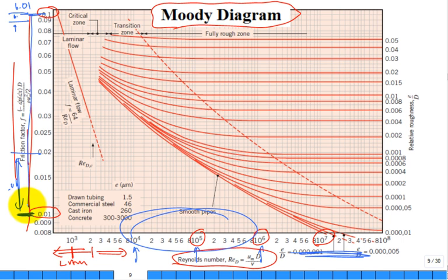Okay? All right. Hopefully you see that. Actually, you could even tighten it down even further, but that just limits it. All right. So now we have this region, laminar flow. The friction factor is a constant divided by the Reynolds number. If you are using the Fanning C sub F, it would be 16 over the Reynolds number.